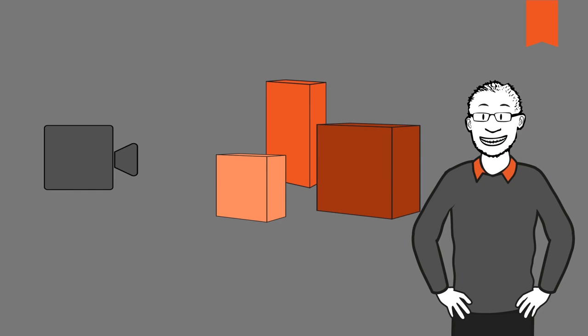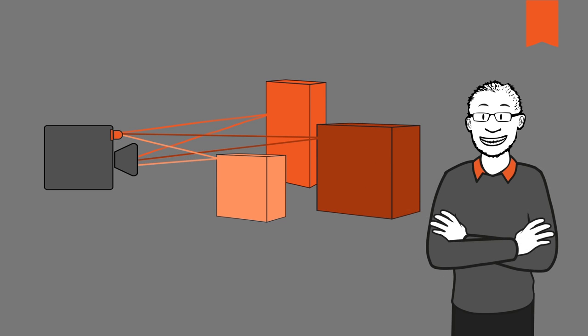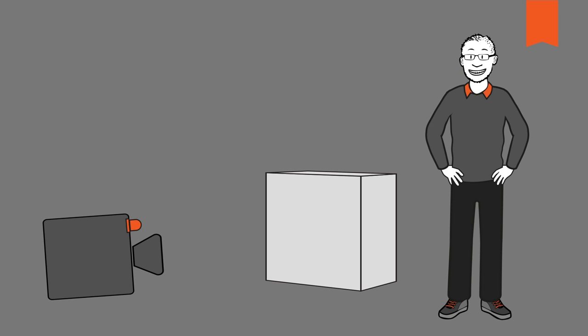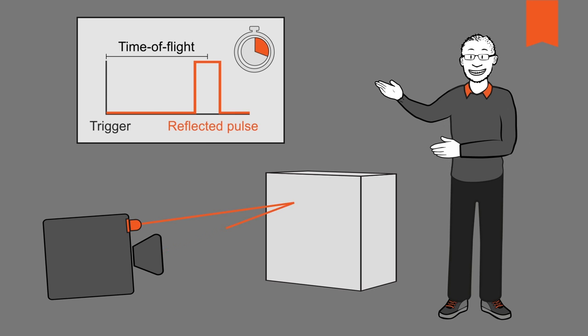In easy terms, a time-of-flight camera works by first illuminating the scene with a pulsed or continuous wave light source and then observing the reflected light. Time-of-flight cameras based on the principle of pulsed light sources measure the time that it takes for a light pulse to travel from the emitter to the scene and then back after reflection. As the speed of the light is known, by using basic math, the distance to all of the points on the object surface can then be determined.